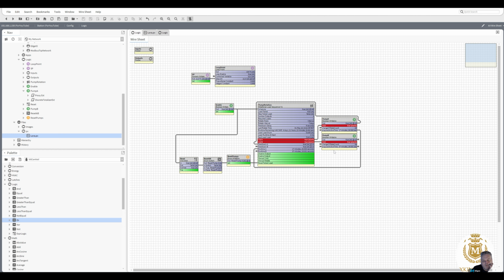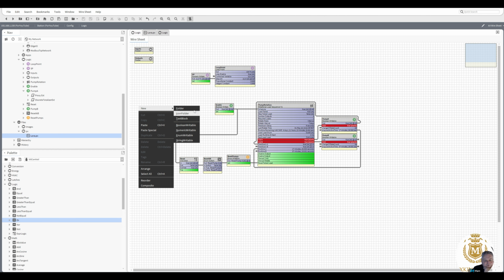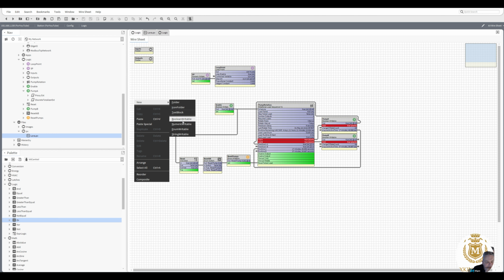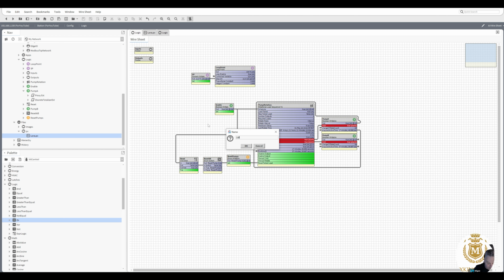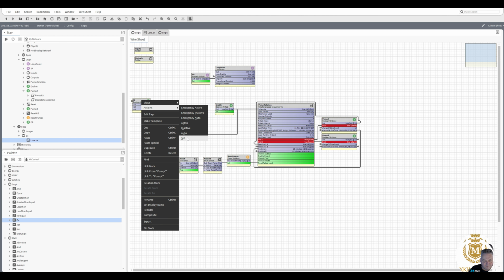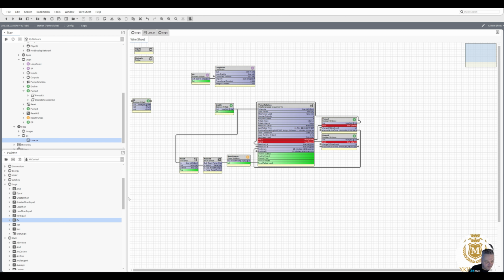Now what I would normally do, if we've got a DP for each individual one, I would have one input going into A and one input going into B. But if I've got a DP for both pumps, let me just make a DP. So that would be your input, for example, from the DP sensor, the flow sensor. And then in this case, I would do some AND gates. And I would do pump A, for example.